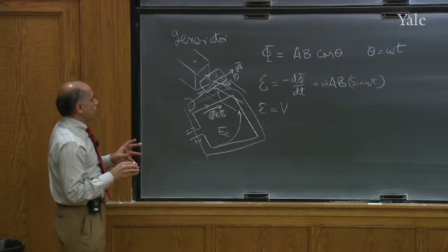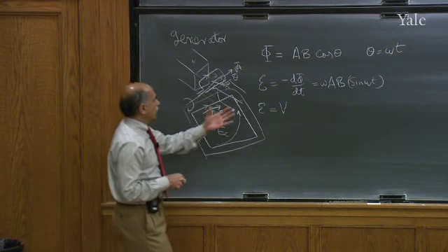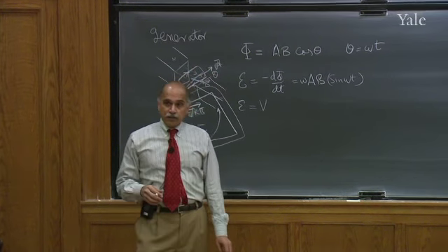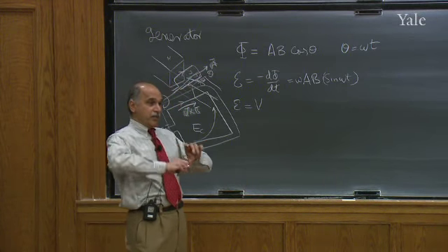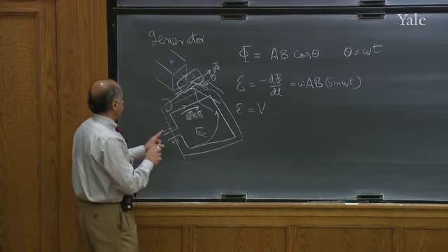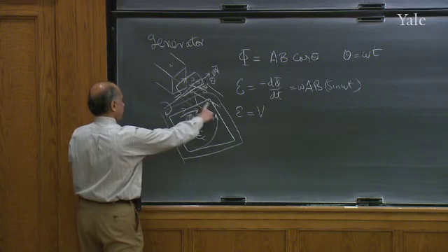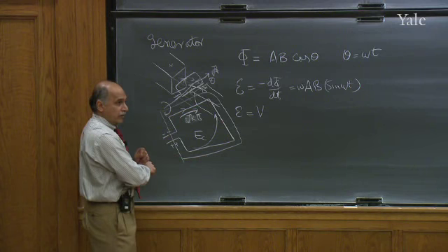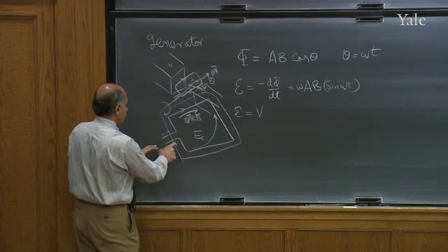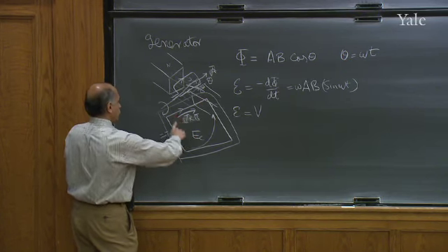So I'm giving you an option. If you don't want to look under the hood, you simply say, whenever you rotate a coil, you get that EMF. That EMF is like a voltage. Case closed. But if you really want to know what's happening inside the wire that made up that coil, the net force on charges inside the wire is actually zero, or an infinitesimal amount is left to make them move this way. That's because the V cross B force is countered by an internal electrostatic force due to pileup of charges that opposes it, so that inside it's free.